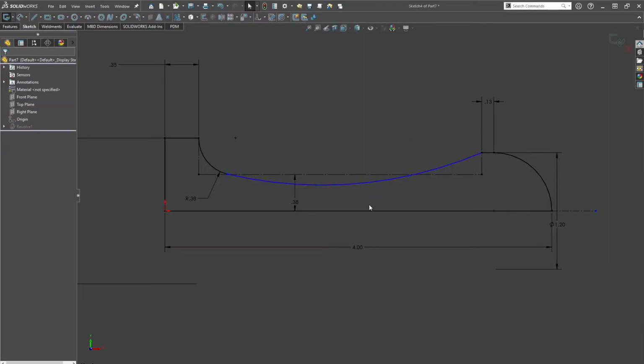Sometimes you'll flip a circle over when it does that, and it's very difficult to get it to flip back around. It can be very annoying when SolidWorks does that. This might be a SolidWorks thing in particular, because of how it indexes the lines for things like relations when you have other things that attach to them.